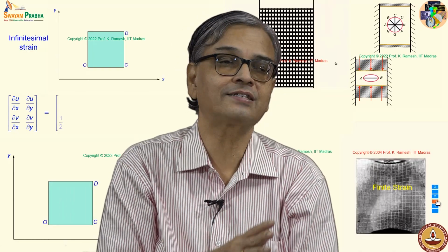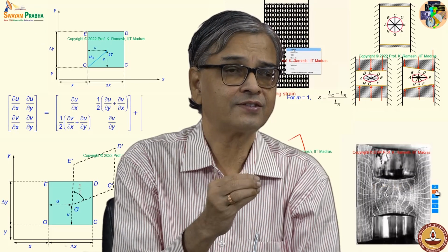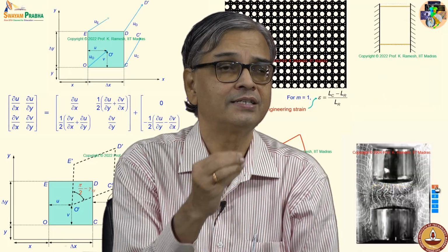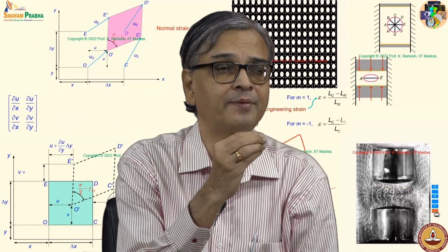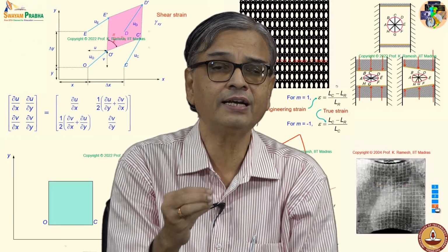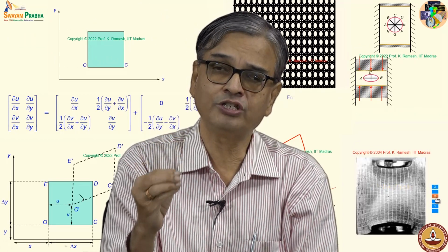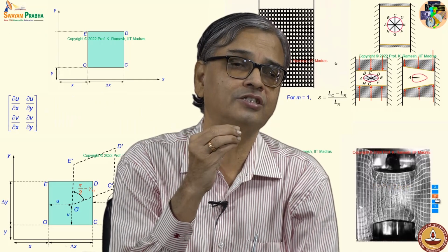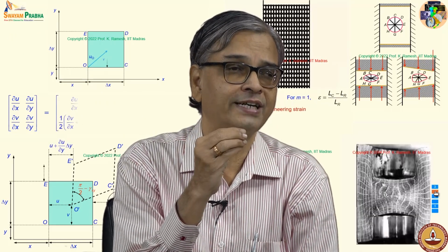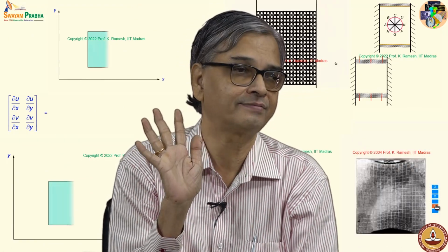So, what you have to understand is, we have looked at stress from the original simple experiment of taking the material with 3 different cross sections. If people plotted on the x-axis change in length divided by original length, and in the y-axis force divided by area, you could get only one line for the given material.